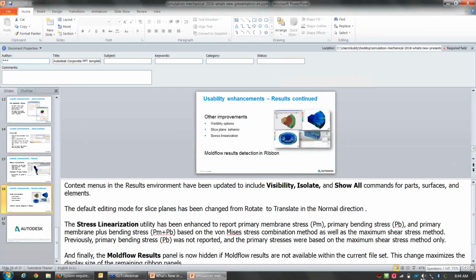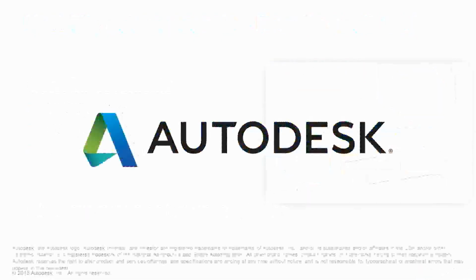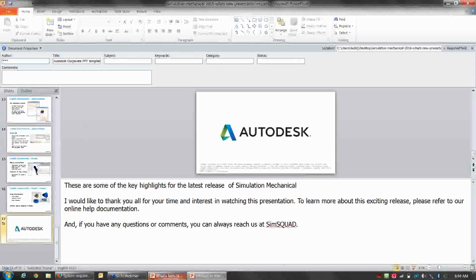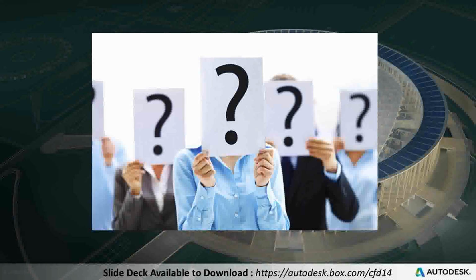Someone was wondering if we can do elastoplastic deformation analysis using this software. Definitely. We can use what's called a mechanical event simulation, or MES analysis, and we can set up some nonlinear materials. This is actually covered a little bit in one of our previous webinars about pressure vessel analysis. We go over doing some things according to ASME code, so I think that would be covered there, and you would just set up a plastic material definition to do that elastic plastic analysis.